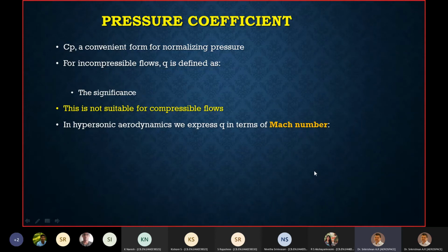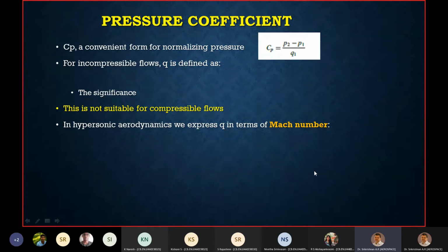Actually, starting from fluid mechanics itself, you have used CP in many flow related or aerodynamics, drag related pressure distribution estimation, where you have considered CP for different shapes, different bodies, different flow conditions, etc. One way to express that is CP as a pressure difference term divided by Q1, where Q1 is the term containing velocity squared.